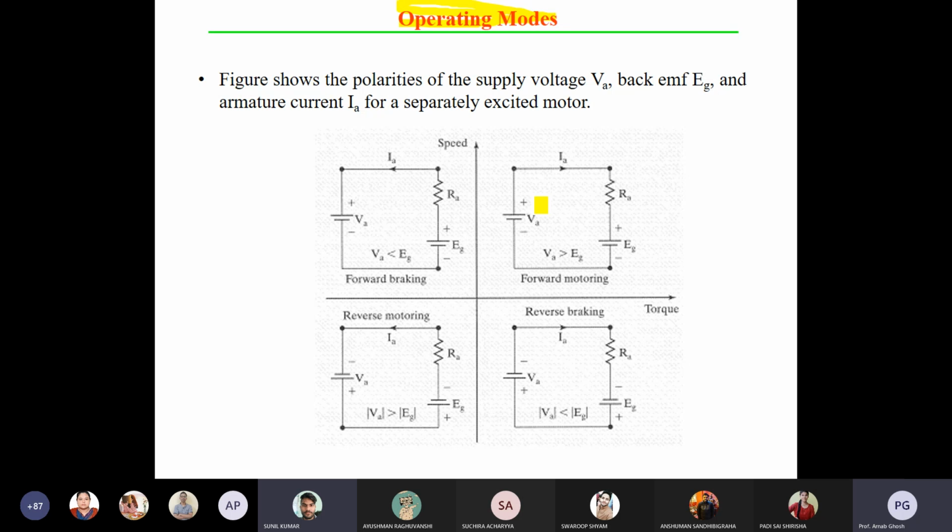Now you are processing the signal, meaning you have a threshold value and the actual signal you are getting. We compare them, and some error signal will be developed. That error signal will again be compared with some repeating sequence, meaning a square, sawtooth or triangular waveform, and at the end of the day you will get some PWM. That PWM goes from your digital platform to your analog platform by a digital to analog converter, a DAC converter.